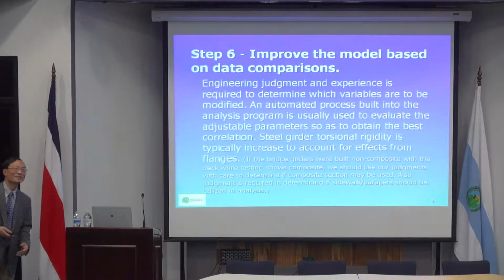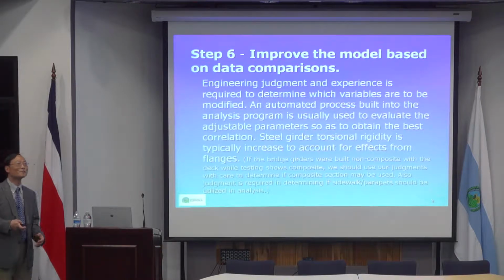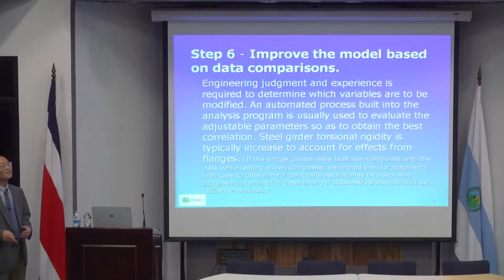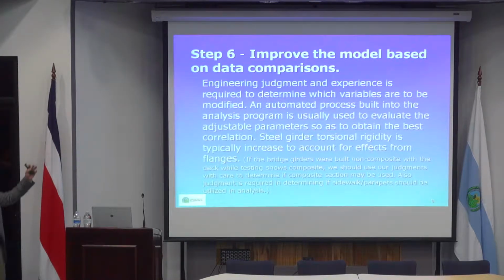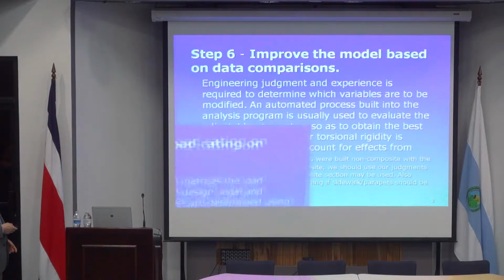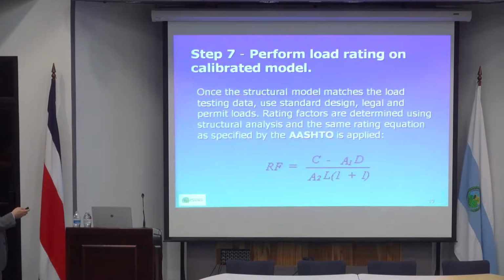And actually, that's very strange. Once I've done that and I do a presentation to the bridge owners, they always have the same question. They say, "Hey, Jim, your model is so accurate. I look at your model outcome and your testing outcome, they are so similar." I said, yeah, they're similar because I use that test to manipulate the stiffness of different elements. So then after that, you use the exact same equations to calculate.